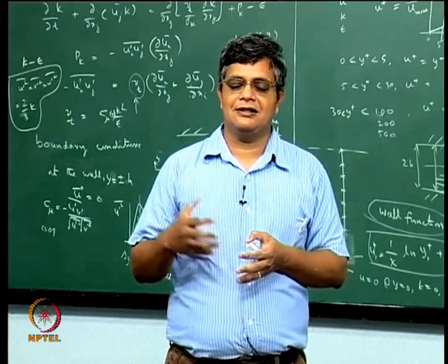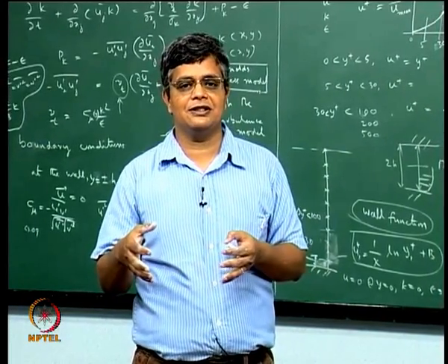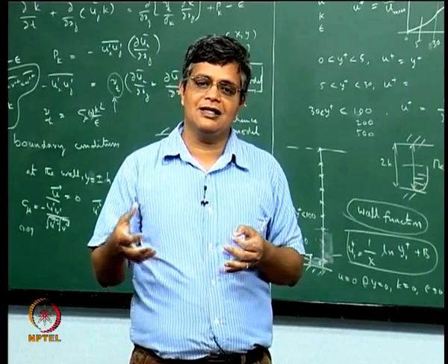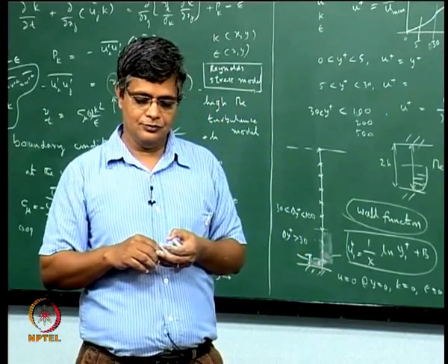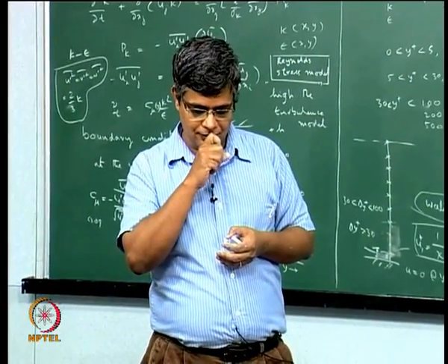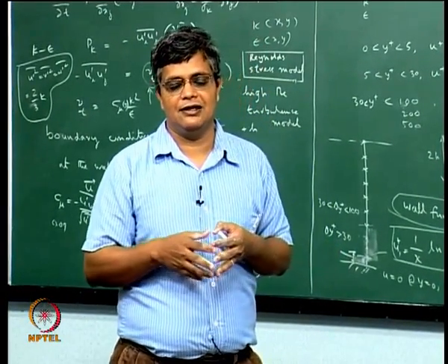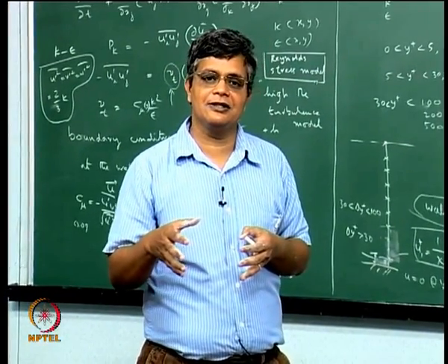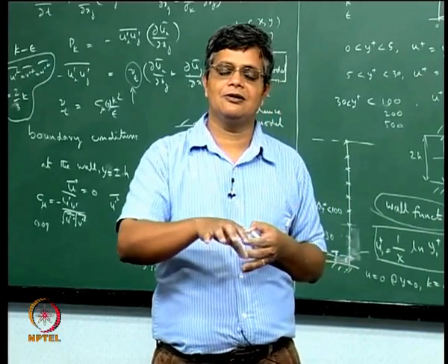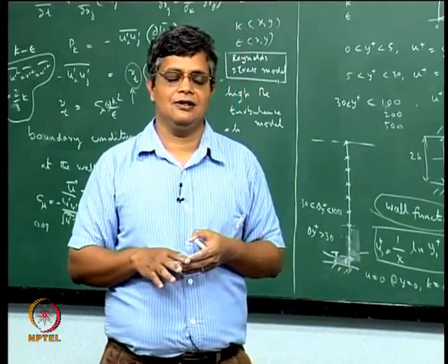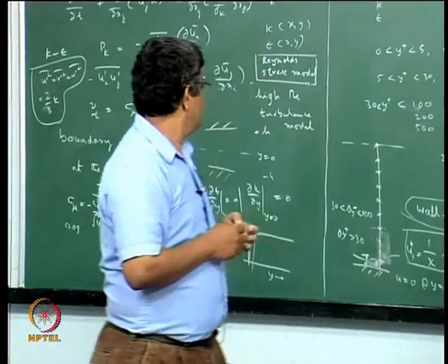The simple answer is that the approach that we have used for the Navier-Stokes equations, for the momentum equations, in terms of Reynolds averaging and then trying to come up with a simplified form of an equation representing the turbulence effect on the overall time average variation of the quantity, is extendable readily to the energy equation for non-isothermal flows and to the species conservation equation for the mass transfer and also chemical reactions.